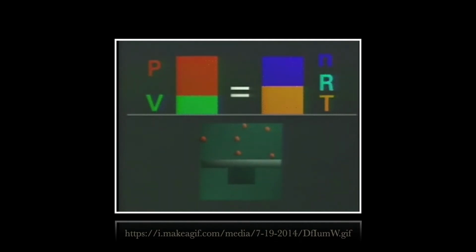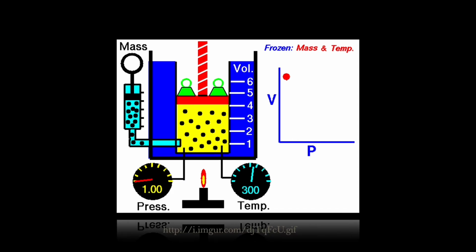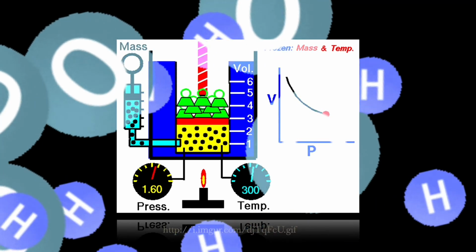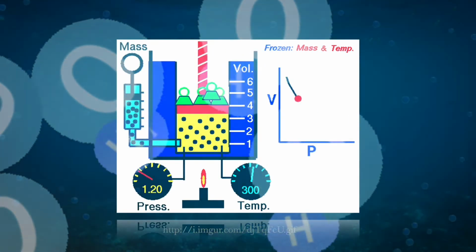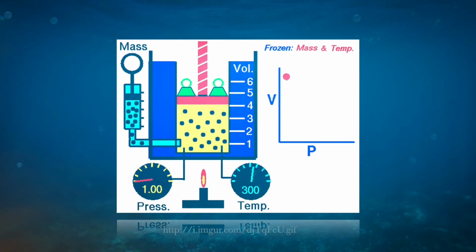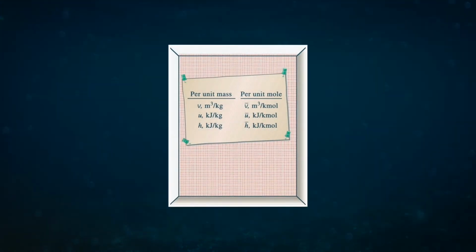It has been experimentally observed that the ideal gas relation given closely approximates the PVT behavior of real gases at low densities. At low pressures and high temperatures, the density of a gas decreases, and the gas behaves as an ideal gas under these conditions. In the range of practical interest, many familiar gases such as air, nitrogen, krypton, and even heavier gases such as carbon dioxide can be treated as ideal gases with negligible error, often less than 1%.